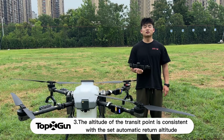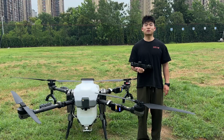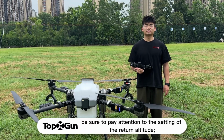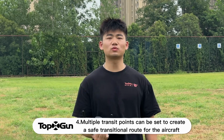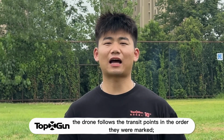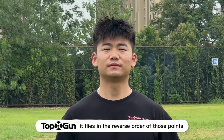3. The altitude of the transit point is consistent with the set automatic return altitude. When using the transit point, be sure to pay attention to the setting of the return altitude. 4. Multiple transit points can be set to create a safe transitional route for the aircraft. When entering the flight path, the drone follows the transit points in the order they were marked. During return, it flies in the reverse order of those points.